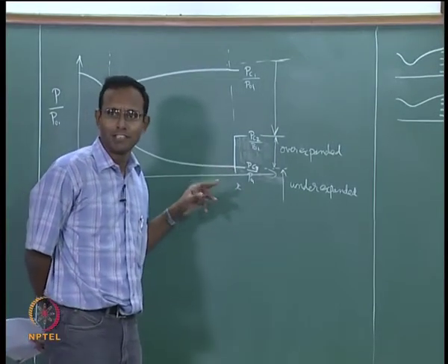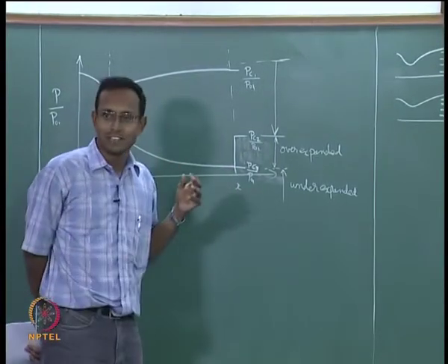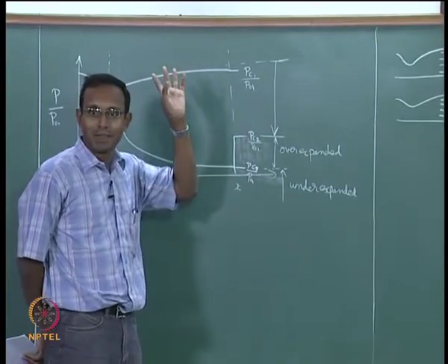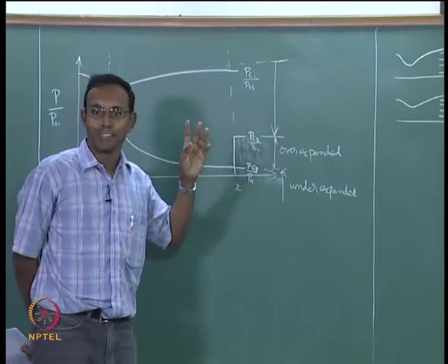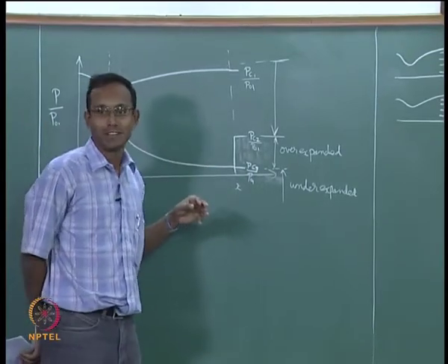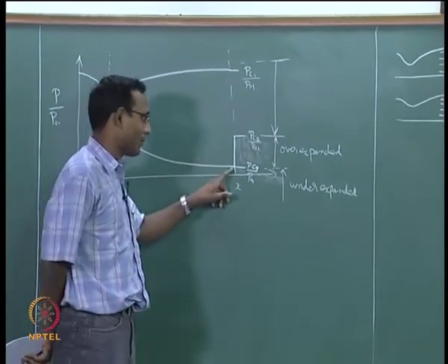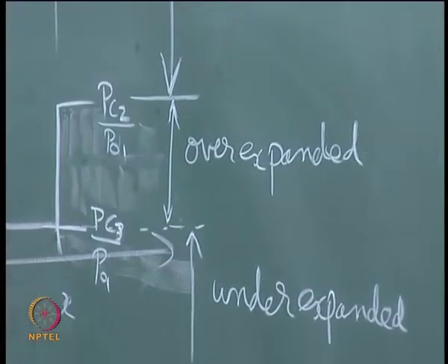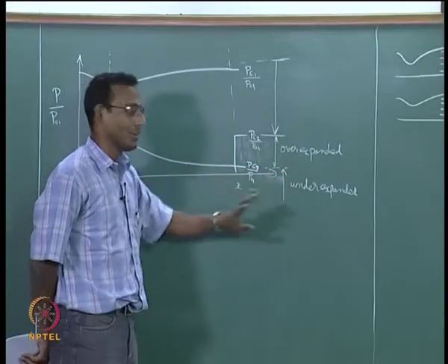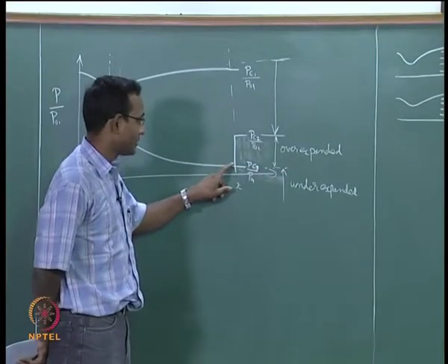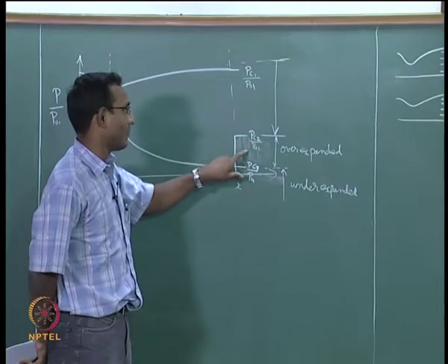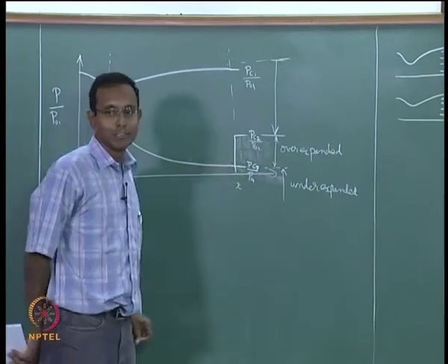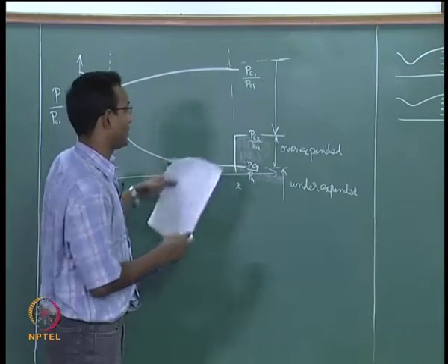Okay, it will be very confusing when you go to propulsion and you talk about rocket is going up, pressure is decreasing outside, but I call it going under expanded operation. It will be opposite if you think about it, but the actual explanation is coming from the point of view of fluid sitting inside at the exit of the nozzle. That is the only way we define this over expanded or under expanded. I am going to say this fluid is much more expanded than what is needed for the outside world. So currently it is over expanded condition. That is what I am going to look at.